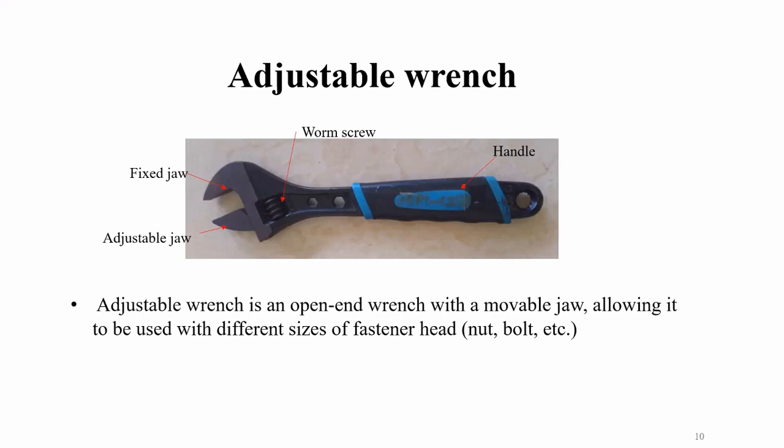Based on the fastening, we can classify it into three major parts. They are temporary fastening, where we are able to join and separate two different metallic parts or tools. For temporary fastening, we utilize nut and bolt. In semi-permanent fastening, we utilize the rivet. If we want to remove that fastening or joint, we have to break the rivet, and after that, that particular machine or part cannot be utilized for further purposes. And in permanent fastening, we utilize welding.